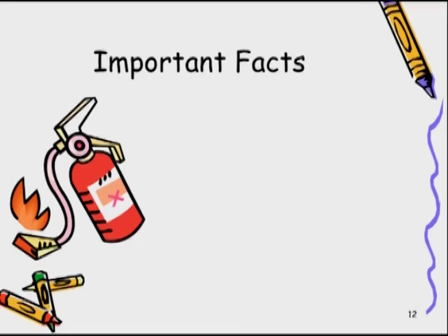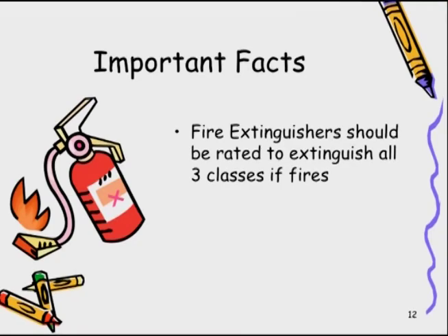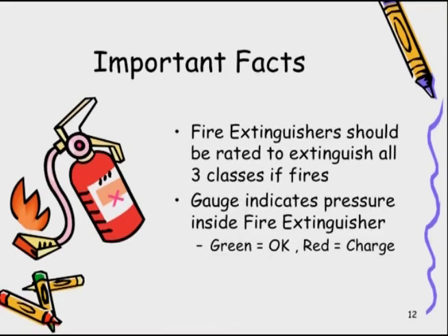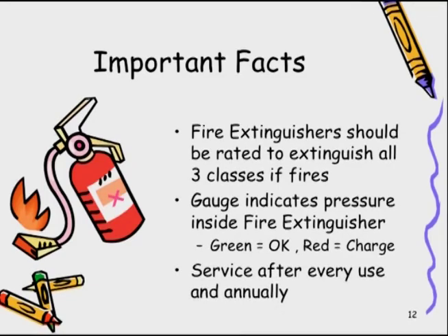Some important facts to keep in mind. Fire extinguishers are filled with a dry chemical and are rated to extinguish all 3 classes of fires. When you check your gauge, ensure it is in the green, and if not, notify your fleet maintenance people. And remember to have your fire extinguisher serviced annually and after each use.